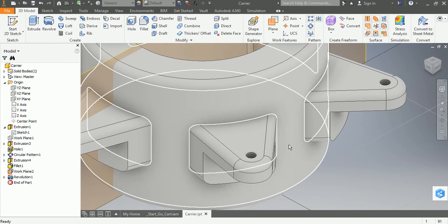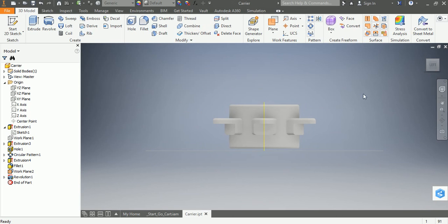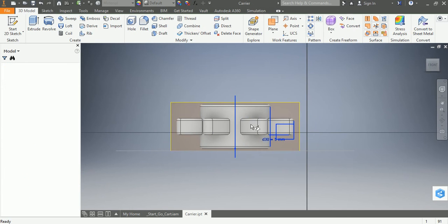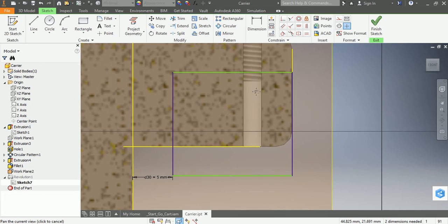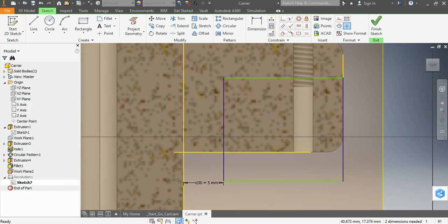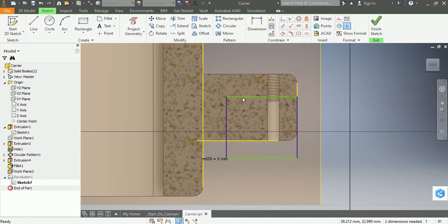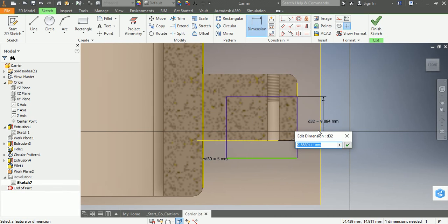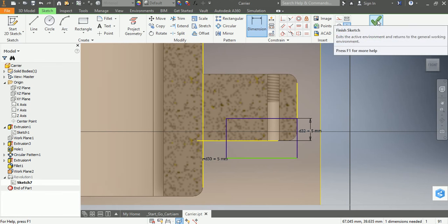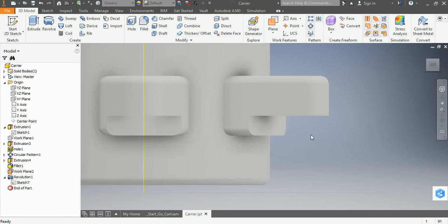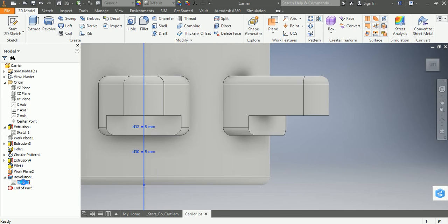And we have our hole now. There you go. In fact, I want to just check something. Going back to this sketch, slice graphics. Yep. Okay. I actually want to choose the dimension of this one. Let's say I want to set it to 5. You can see the revolve will automatically update.